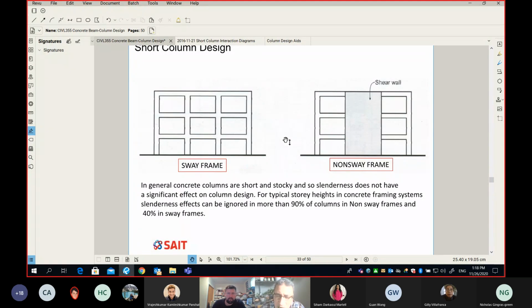They have a big shaft in the center of the building, and this shaft is simply the core of the building that restrains everything from motion laterally. During construction, typically they advance the shaft before even the floors get in. First the shaft, then floors next.